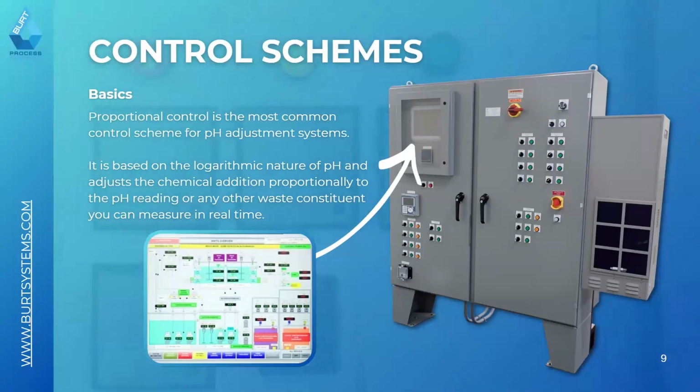So you're going to measure some volume in your tank. You're going to put in your sanitizer, whether that's bleach or a hypo injection, for a specific dwell time based on a volume. You want to get 500 ppm or 1,000 ppm to allow you to go through that kill process. For pH, you're solely basing it on the pH curve at that point.